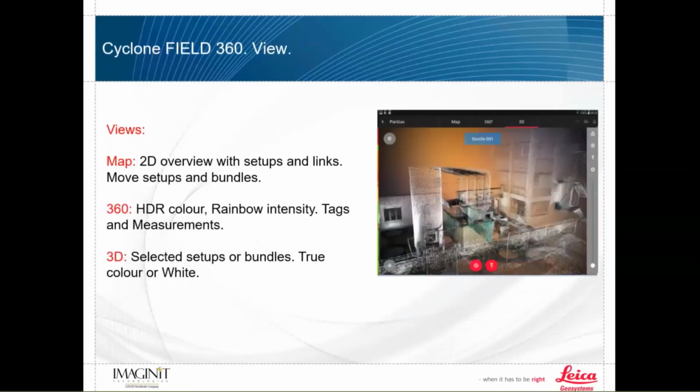One thing I did want to point out that we forgot to put in here is in the lower left-hand corner, there is a fairly new tool. It's been out a little bit, but I am now able to fly through the point cloud using the fly-through tool. The navigation is a lot like a video game, but it does allow me to do that navigation.